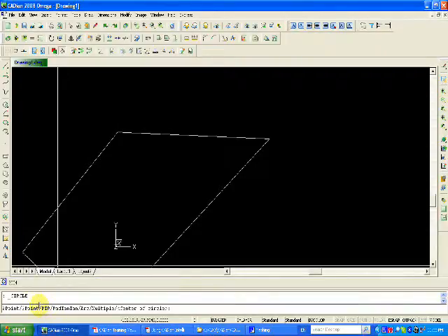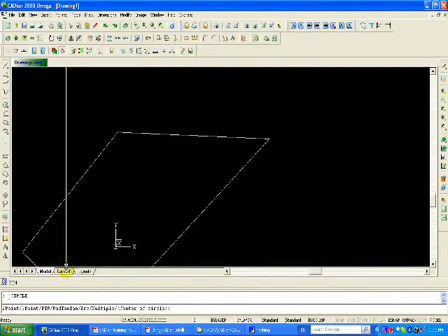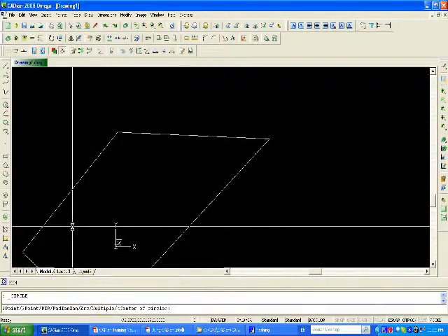Now, the little hint here, the first digit or number: if, for example, you want to draw a circle with a radius and 2 tangents, if you type in R, that's what it's going to choose. And then multiple will be multiple circles. Just type R and see what happens. It asks you for the first tangent point.